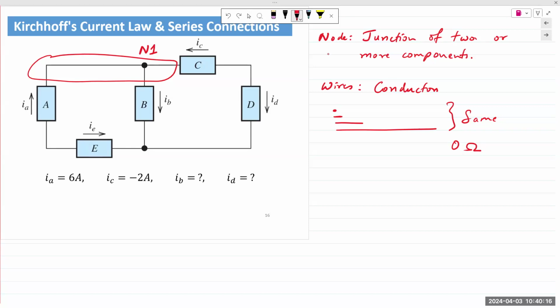But anyway, the point being that if you plug a 100-foot extension cable into a power outlet, 100 feet away you would still expect to get 120 volts. It might be 119, 118 perhaps, but it does not rise to the level of interference, meaning it's not going to fall to 50 volts so that your device doesn't work. Every cable, every conductor, even a simple cable like this, has resistance, inductance, and capacitance. But the values of those quantities do not rise to the level of interference.